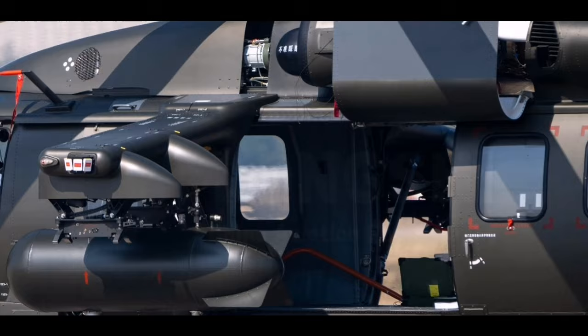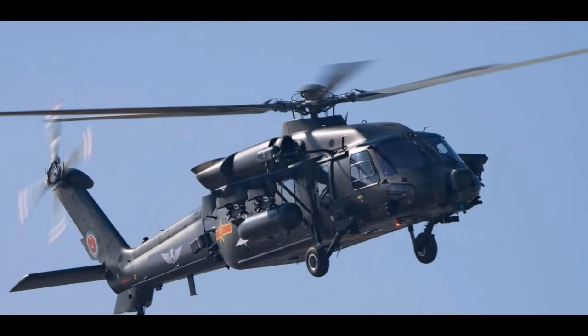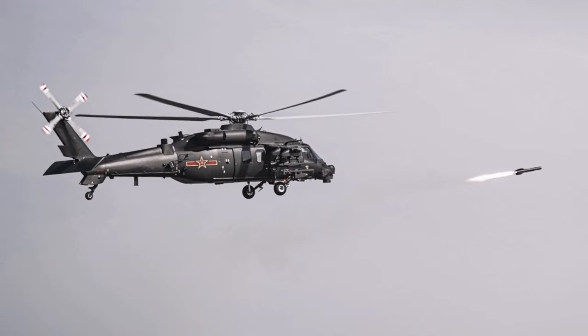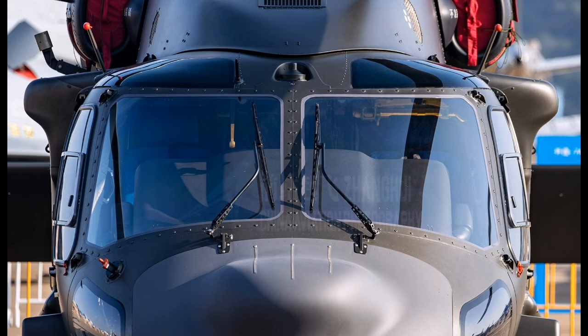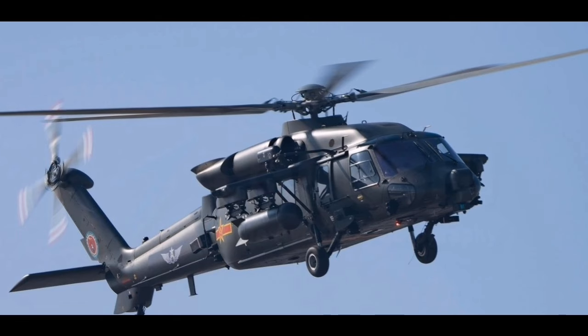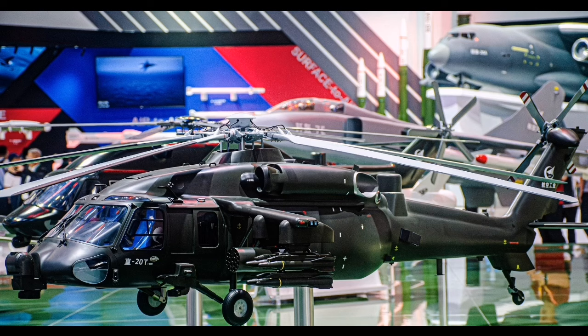It can be programmed to provide inherent flight stability, automatically damping out turbulence and preventing the pilot from inadvertently exceeding the aircraft's safe flight envelope. It significantly reduces the physical workload on the pilots, especially during long, low-level flights, and it allows for flight control laws to be optimized for different phases of flight, such as a very stable hover mode for weapon deployment or a more responsive mode for nap of the earth flying.